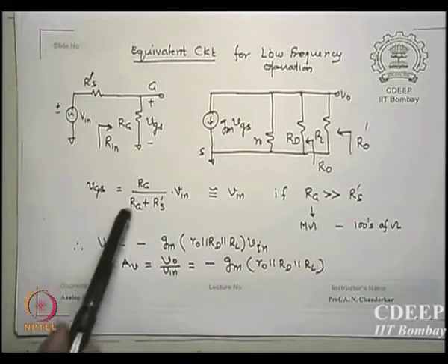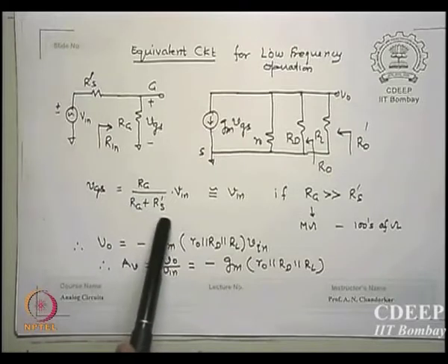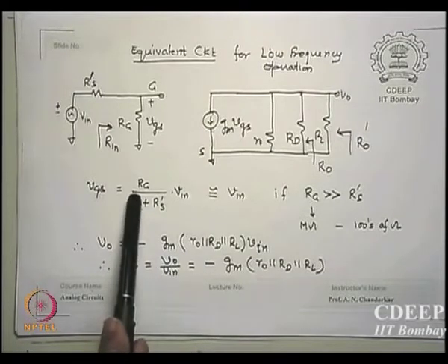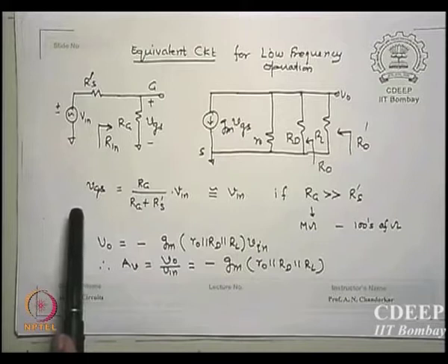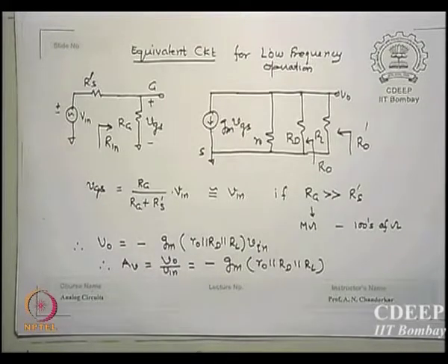Since there will be something in the denominator larger than the numerator, VGS will be less than Vin, but it may be 0.9999 Vin, so why should I worry about 0.9999, I say Vin. So the idea is to know when to use what. These are all things which I am trying to show you in real circuits.